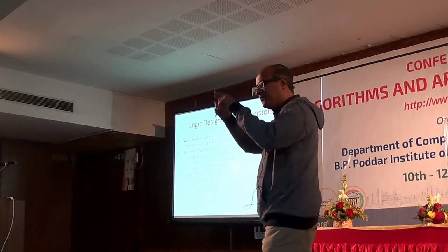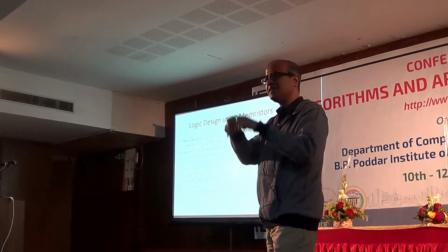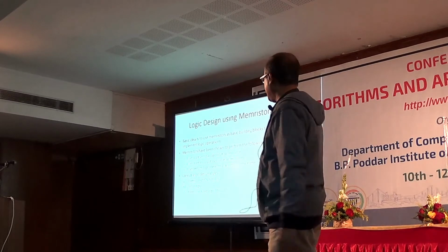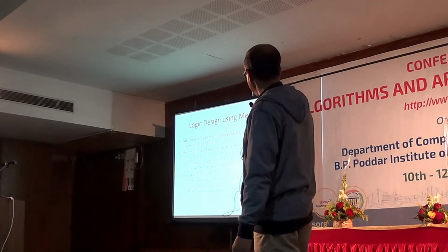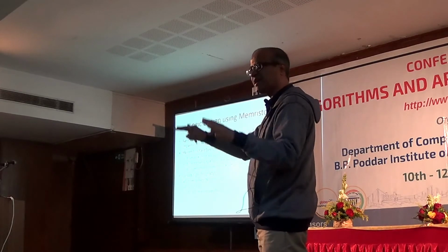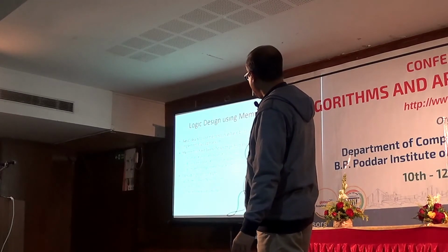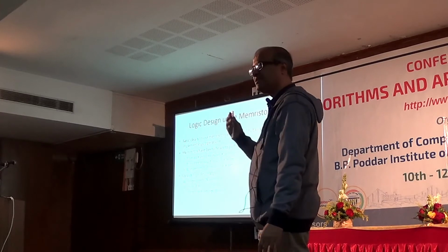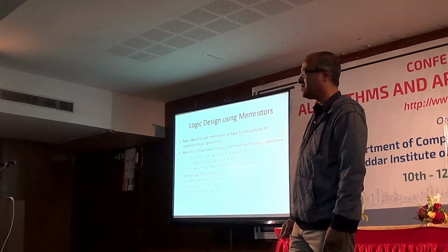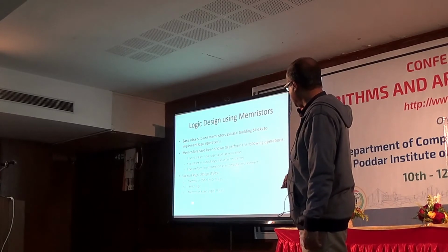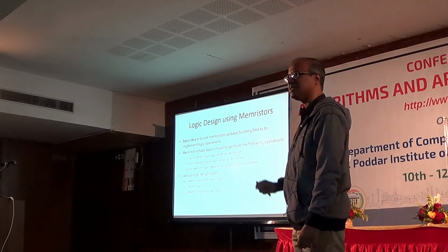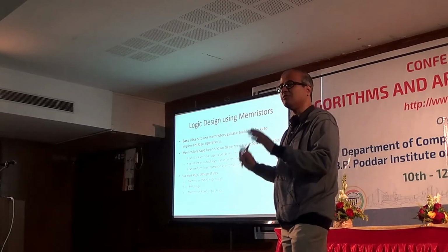Now, if we have a memory system like that in the form of a crossbar, a lot of work has been done where it has been shown that memristors fabricated on a crossbar can be used to implement certain kinds of logic operations. There are many works. So we shall be briefly looking at 2 of them, IMPLY and MAGIC. Let's see how they work.